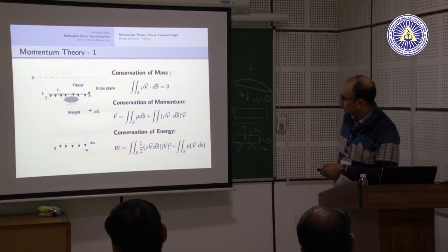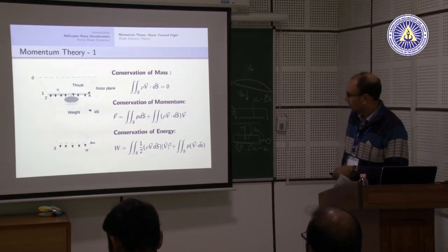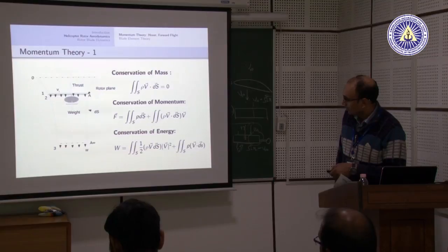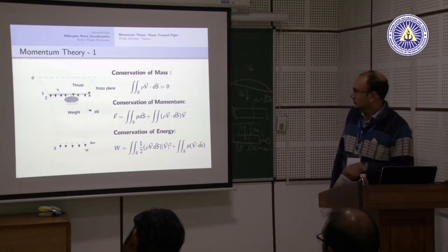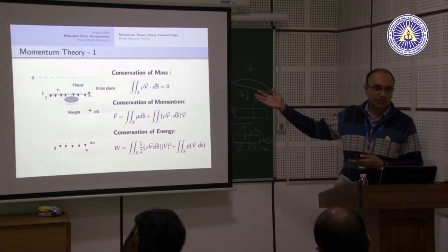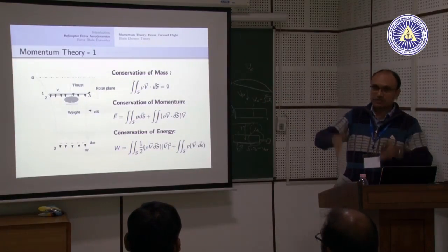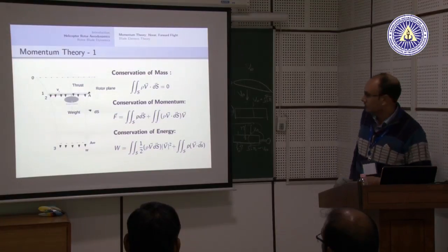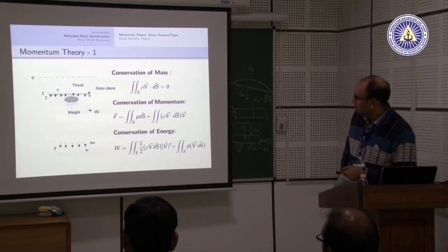The velocity induced at the rotor is Vi, which we call the induced velocity, and then there is the velocity which is exiting in the slipstream. The boundary which we have created from 0, 1, 2, 3 up to here is called the slipstream, or the boundary of the flow, which you were able to see physically. When we saw the video, the smoke gave us a very nice visualization of the whole slipstream boundary for the wake of the helicopter. We have that same thing here, and different areas.